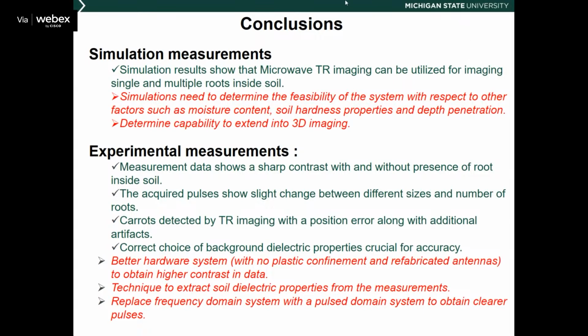Okay, microwave sensor. Let me open this. Can a microwave sensor detect nanometer or micrometer range dimension defects in material? The answer is yes. Actually, the paper came out a few decades ago, but that's limited to a very small field of view. You can have a nanometer resolution microwave sensor. Those are cantilever or tip-based sensors in the near field. If you Google near field microwave, you'll see those setups there.